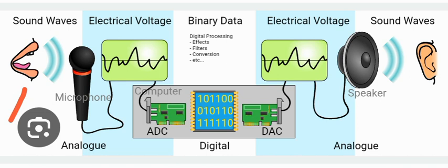Now we need a typical electronic system to process this kind of sound waves or acoustic signals. So these signals, the sound vibrations from my side, can be picked up by a transducer or electronic gadget called a microphone, as shown in this picture. What the microphone does is that it receives the sound waves and converts them into proportional electrical voltage, as shown by this graph over here.